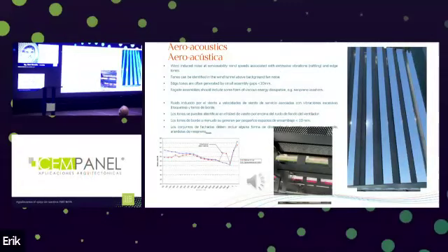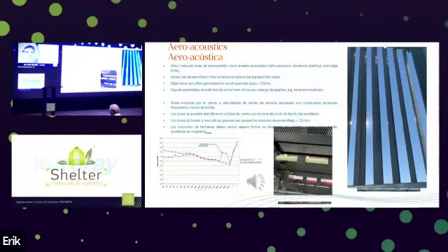Aeroacoustics. Now, wind noise is also a serviceability issue, and it's typically associated with rattling. We all experience a loose facade element, a sliding screen, for example, rattle in the wind. In itself, that's annoying. But we can also have these edge tones, which is a very similar mechanism to the loading we were just talking about, but rather than produce a load, it's very high frequency, in the order of thousands of hertz, creating a noise.